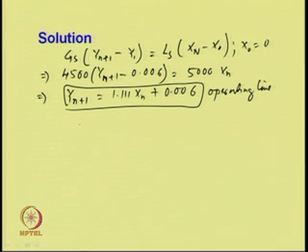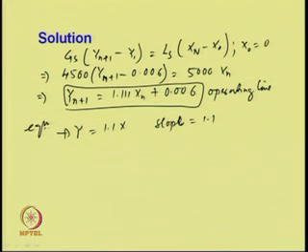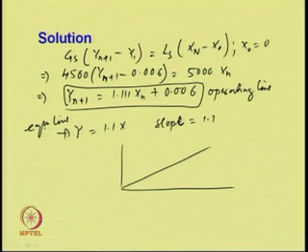So, we know the equation of operating line, and we know the equation of the equilibrium line, 1.1 x, with a slope 1.1. So, we know the slope of the equilibrium line. This is the equilibrium line. Then, like the previous method, we can graphically obtain the number of stages by plotting vertical and horizontal lines.